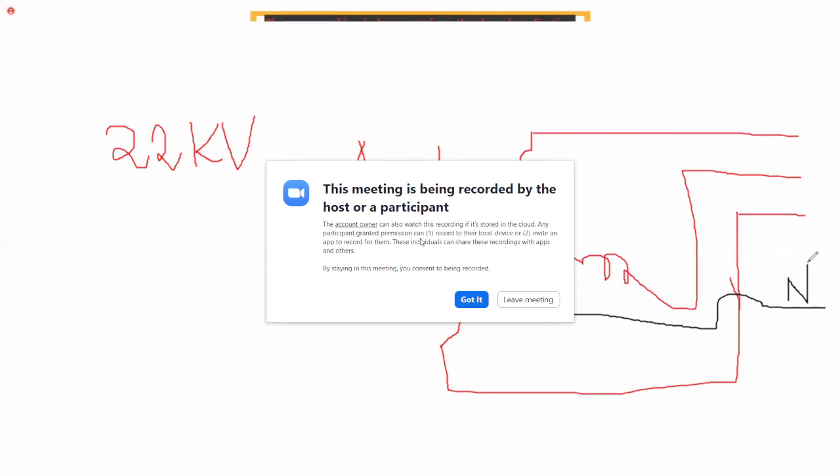Is it true or false? Can you repeat the question? The question is: line voltage is 440, phase voltage is 230. Is it stepped down? Yes, true, sir. No, you should say it is wrong. We just pick up one phase and one neutral. Nothing is stepped down; it is 230 by itself. Okay.